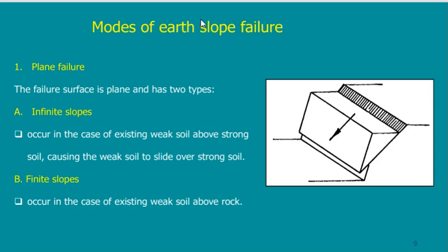But this is what I mean, that in any case, in slope stability or in many other cases, to study it, we have first to assume a shape for the failure, see what are the forces that are pushing this shape to fall or to fail, and what are the forces that are keeping this shape in place. Take the factor of safety.